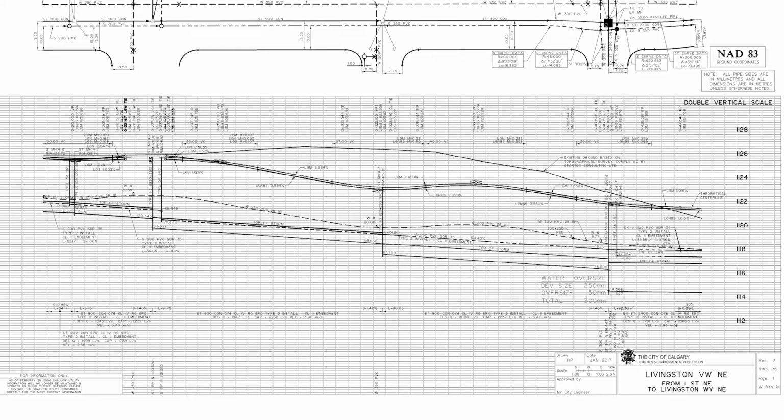As we mentioned before, profile refers to a side-on view along the road. Again, there is a bunch of lines and words which can look intimidating, but we'll break it down into individual components. The first line we'll look at is existing ground. This is where the ground was as the design process began. It helped the designers use the material on site most effectively.